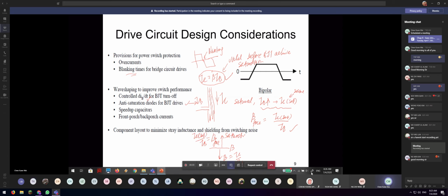So this will give you some basic difference after they achieve saturation. Saturation means the channel is already full, and you cannot increase IC anymore. It is overloaded. If I operate my circuit in full saturation mode, it is very hard for me to remove the charge inside.